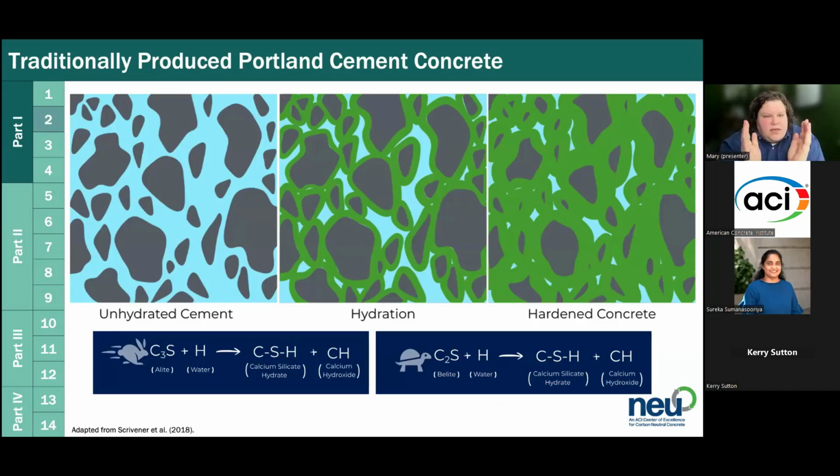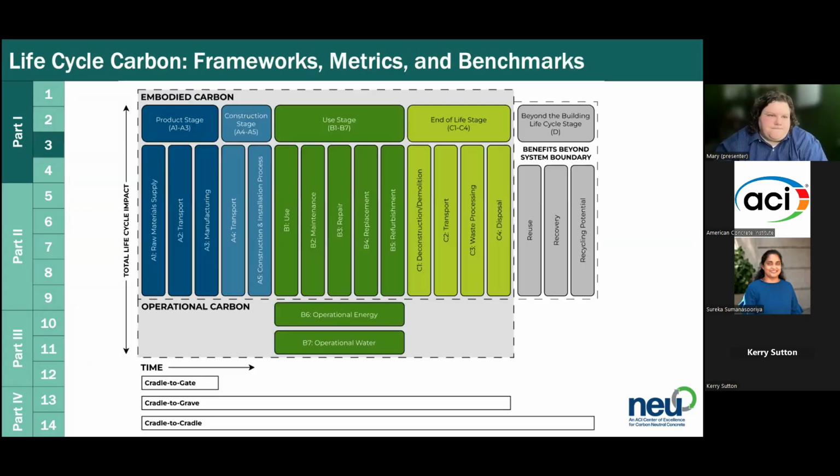But chapter 2 also includes an overview of hydration. That's when the cement, in gray here, mixes with the water, in blue here, to form the phases that make the concrete hard. We go through a bit of the chemistry. We tried to keep it very palatable in that chapter, but enough so that you could understand how alternative cements or other materials that do alter the chemistry differ.